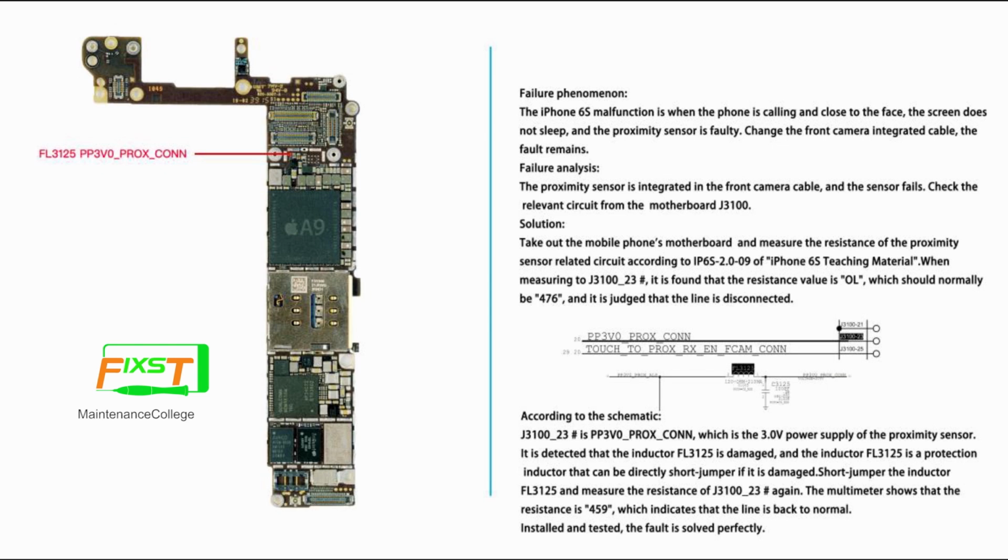This is an iPhone 6s. The proximity sensor has some problem. When we are calling close to the face, the screen does not sleep, which means the proximity sensor has failed. And we changed the FaceTime camera cable, which also had some problem. So according to our earlier class, you will know that when we meet this problem, after we change the cable and it is not fixed,